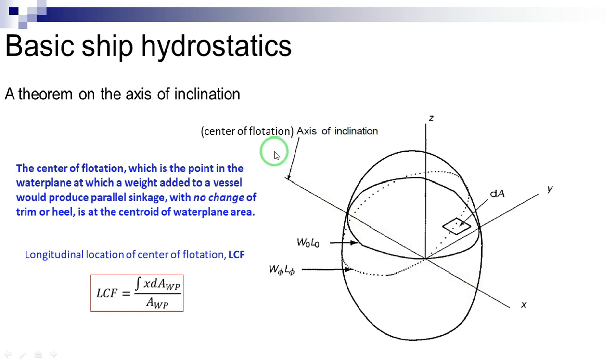In practice, this property holds if the angle of inclination is sufficiently small. For heeling of a vessel, this can mean a few degrees, up to 5 degrees for some forms, even 15 degrees for others. If the inclination is the trimming of an intact vessel, the angles are usually small enough, and this property always holds.